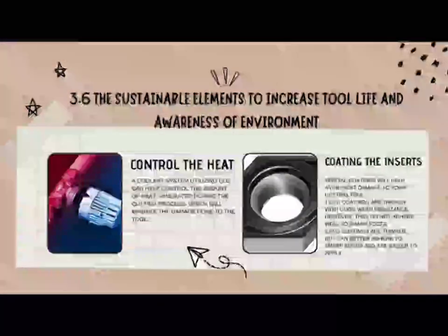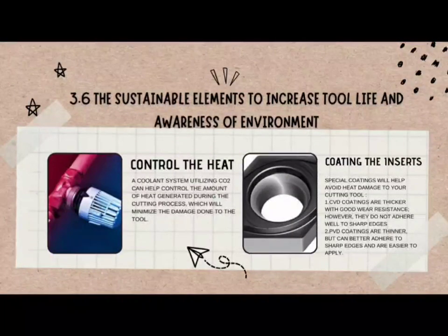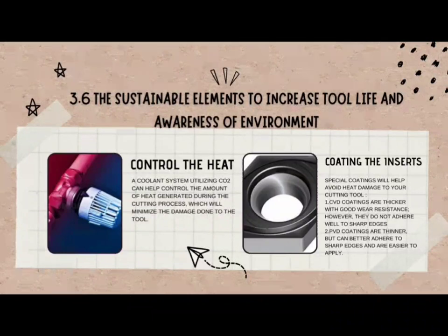3.6 The elements to increase tool life and awareness of the environment. Firstly, control the heat. The coolant system utilizing CO2 can help control the amount of heat generated during the cutting process, which will minimize the damage done to the tool.